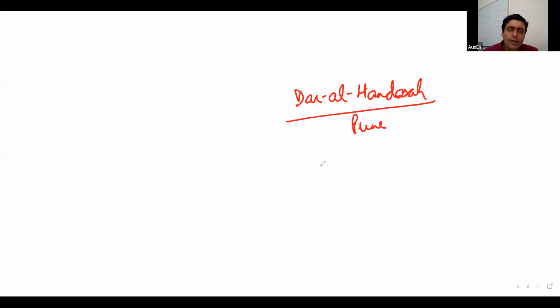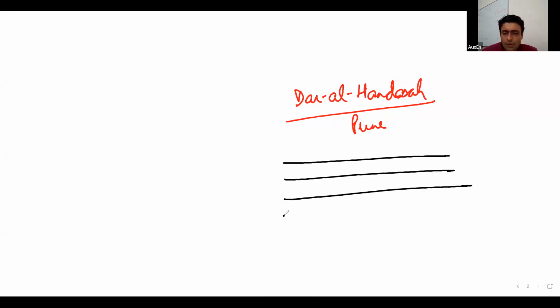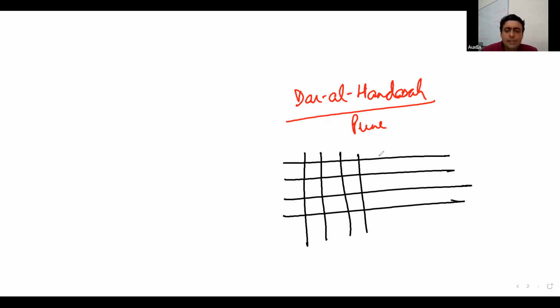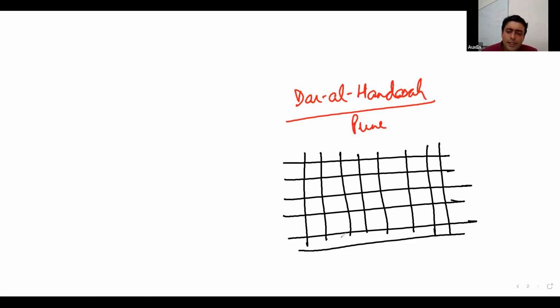There they are not very much, I would say, concerned with the cost of your project. All right. So they have a lot of money to spend, a lot of petroleum dollars. So they are not very concerned about the cost as such. So we used to provide all reinforcements that we used to provide. We used to do mainly RCC designs. So all reinforcements that we used to provide would be a mesh-like reinforcement. All right. In slabs, it would be a mesh, top-bottom mesh, both directions.